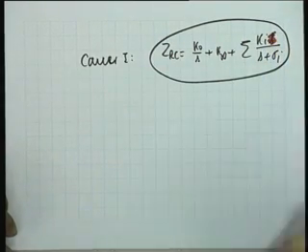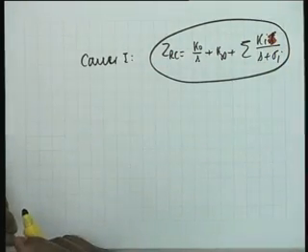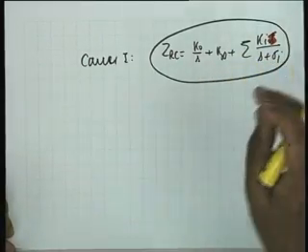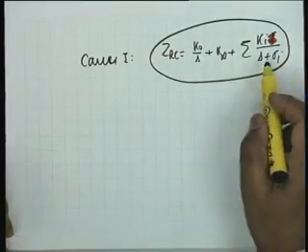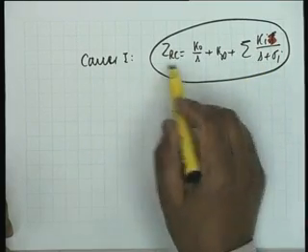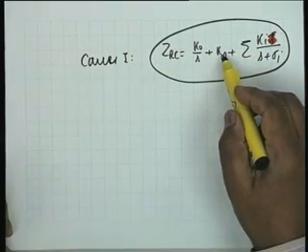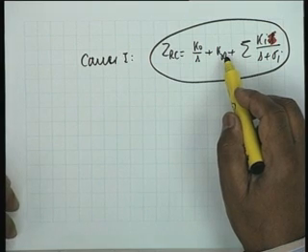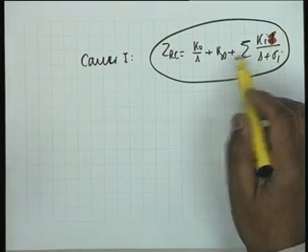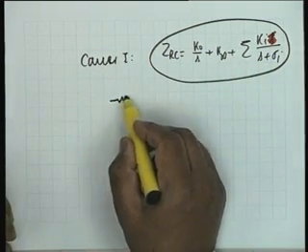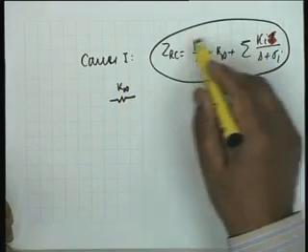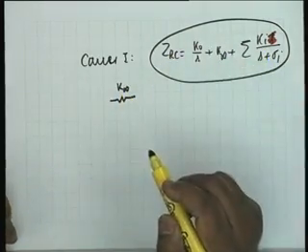No S. All right. Now, Cauer 1 concentrates on the point at infinity. You see, at infinity what ZRC can have is either a constant or a pole. Now, this constant can be removed without affecting the rest of the function. So, I remove K infinity. If I remove this, then what will be the behavior of ZRC at infinity?